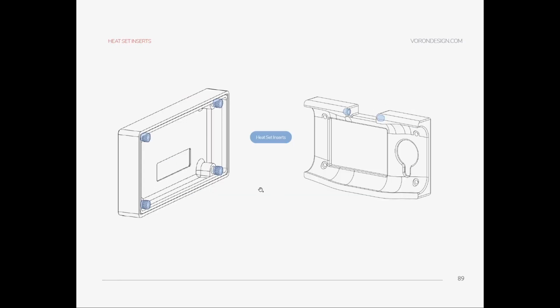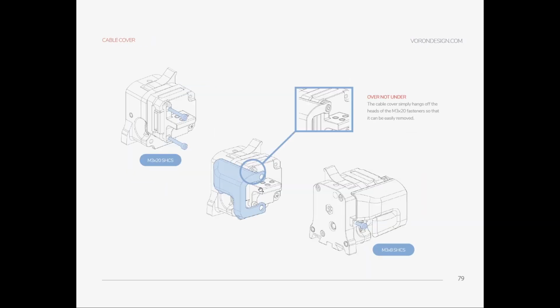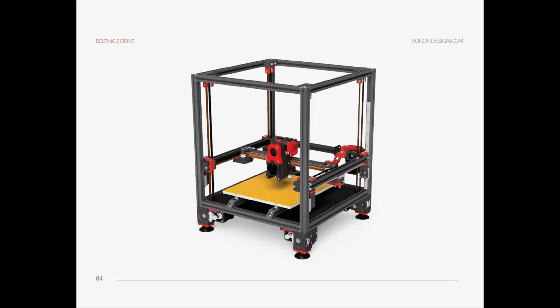So you ran your Z belts. Where are we? Oh, yeah. Now you want to do the gantry racking. For that, put your gantry level in a way, by measuring in one corner, for example, adjust it 20 centimeters from the top of the rails to the gantry, and apply the same measurement to all. So your gantry will be square in a way.